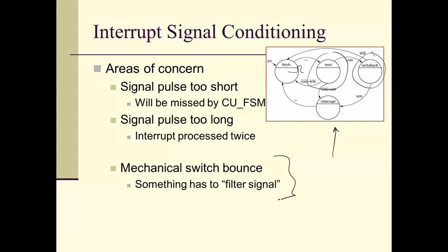Now buttons or a switch, they're mechanical devices. You know, they have contacts. When you actuate the button or switch or deactivate it, the switches or the contacts bounce. They actually bounce no matter how soft you press the button. The contacts are going to bounce. It's totally weird. But anyway, so we have to deal with that also.